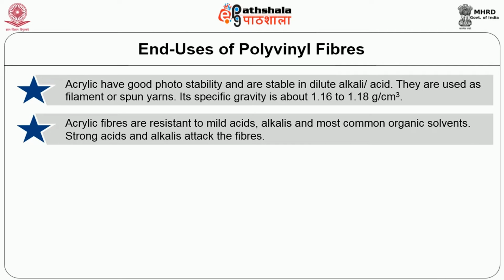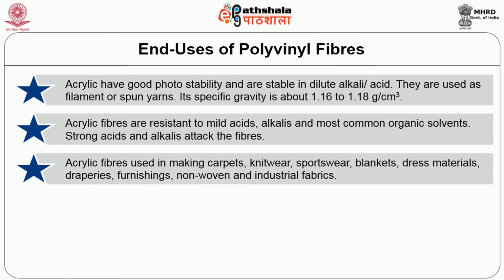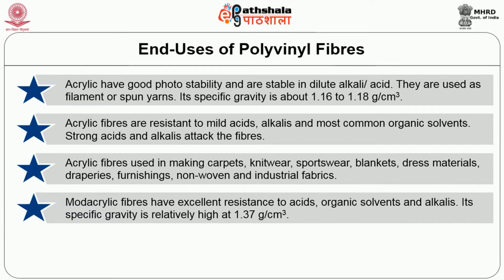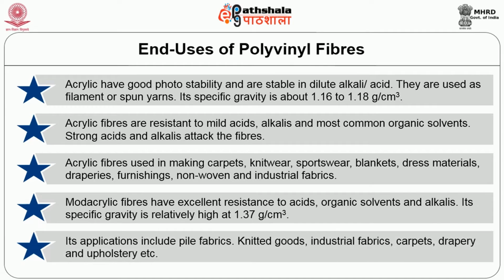Strong acids and alkalis attack the fibers. Acrylic fibers are used in making carpets, knitwear, sportswear, blankets, dress materials, draperies, furnishing, non-woven and industrial fabrics. Modacrylic fibers have excellent resistance to acids, organic solvents and alkalis. Their specific gravity is relatively high at 1.37 grams per cubic centimeter. Their applications include pile fabrics, knitted goods, industrial fabrics, carpets, draperies and upholsteries, etc.